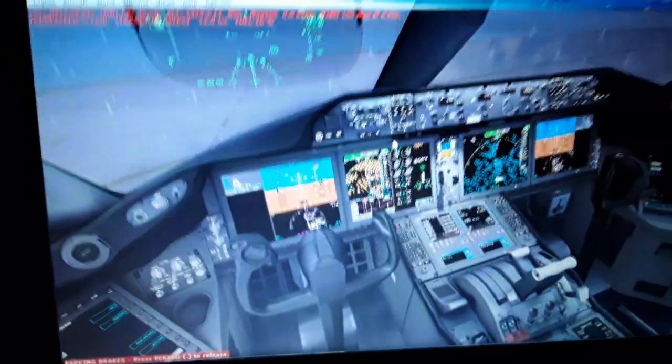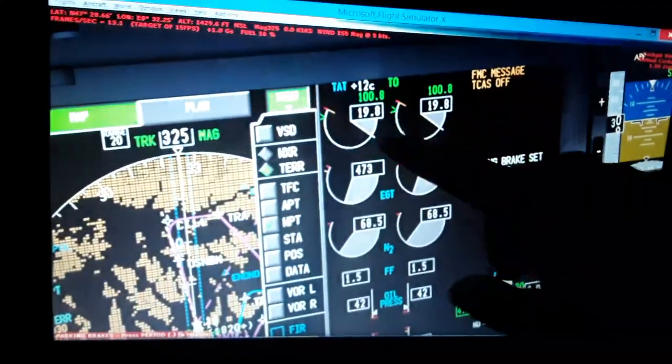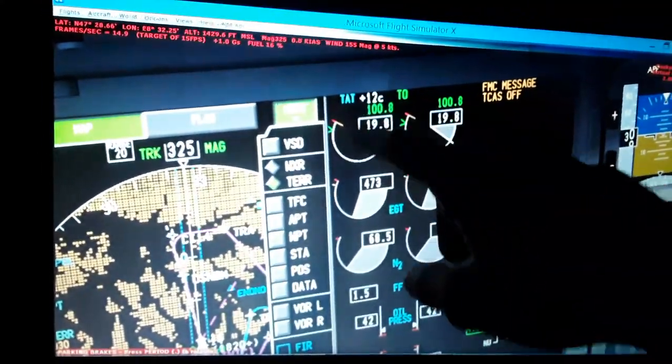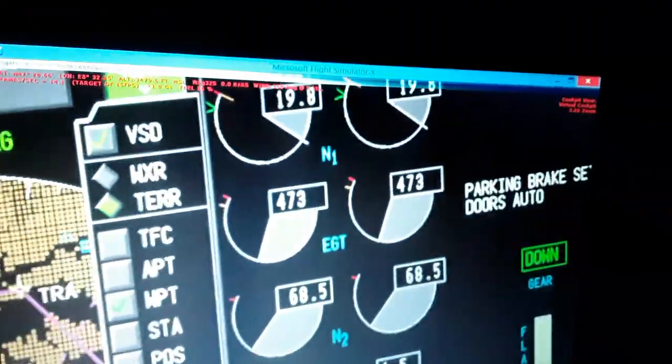One is installed per engine gearbox, and it controls, monitors and displays all the engine data using the upper or the lower EICAS, the engine indication and crew alerting system display of the Boeing 787-9 aircraft. So we have a display here, the multifunction display or EICAS display. You can see the engine data, like the N1, which is the low speed shaft, the low pressure compressor and the turbine of the turbofan, for the engine on the left and the right.